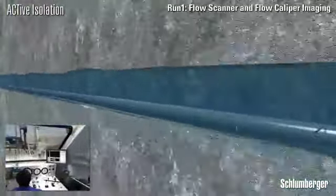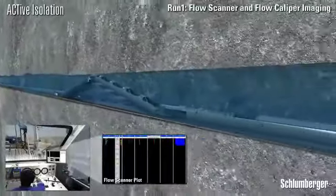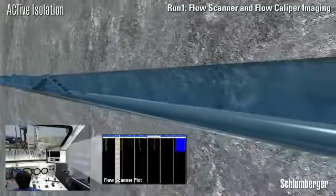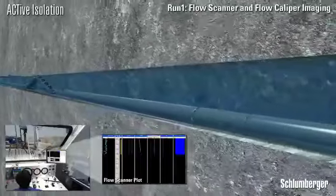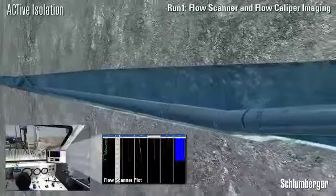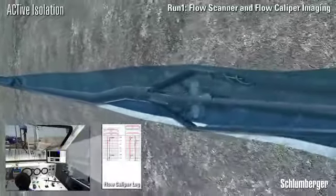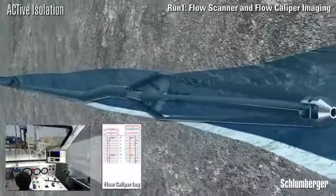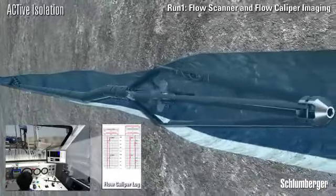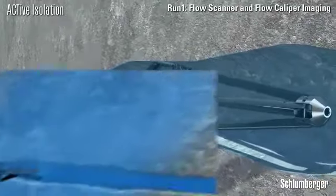As part of the active production services, the flow scanner system collects flow profile and holdup data, and the flow caliper imaging tool collects X and Y data of wellbore geometry. Both are plotted against the gamma ray profile. Downhole pressure and downhole temperature are also confirmed on this run and used to design the cement slurry. These data are sent in real time by active production services via fiber optics to the surface. Collected logging data can be reviewed in real time at the location and remotely at the office.